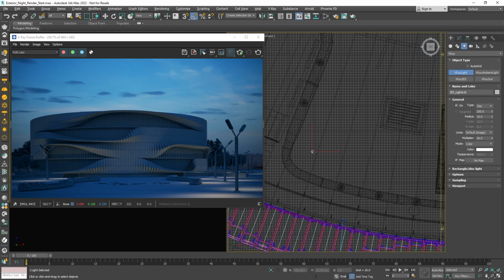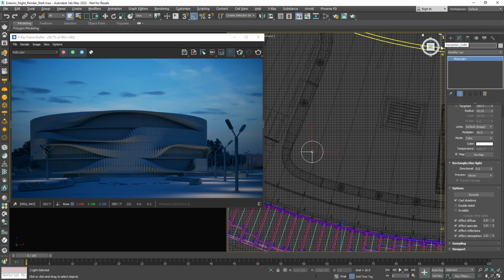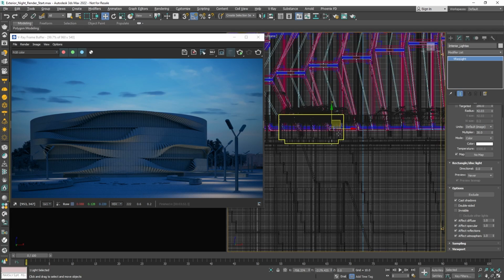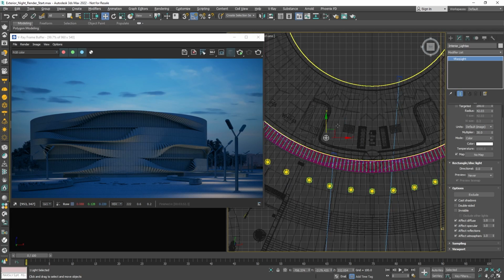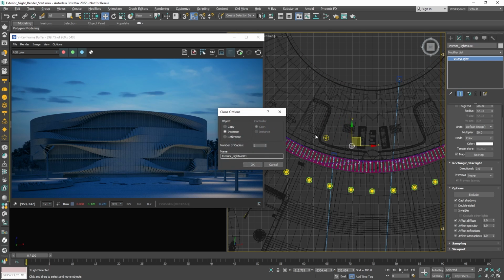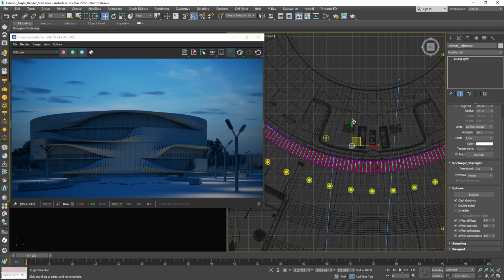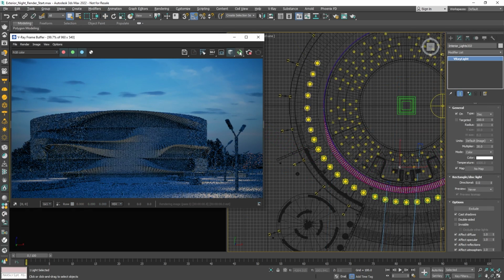For that, we'll use the V-Ray disc light. Create one from the V-Ray toolbar and let's place it in the scene. Name it appropriately. For the interior lighting, I will rely on small sources placed around the ceiling of the building on every floor to better imitate the lighting in a building. That's why I will set the radius to 15 and instance the light all over each floor of the building. The lighting setup can also be simplified with fewer, larger sources of light.